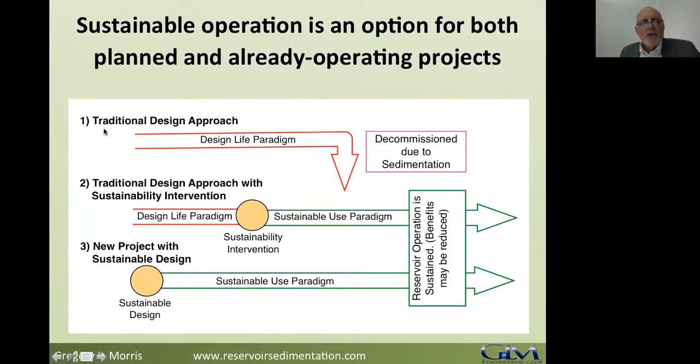The reservoirs in the United States and most areas of the world have traditionally been designed using the concept, or the paradigm, of a design life. Under design life, you're looking at a 50 or 100-year design, and you design a sedimentation pool for that capacity. You don't really worry about what happens later. That's someone else's problem. You assume it'll be decommissioned. It's not the designer's problem.